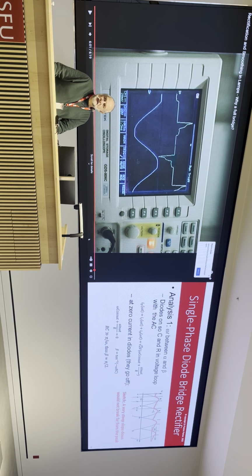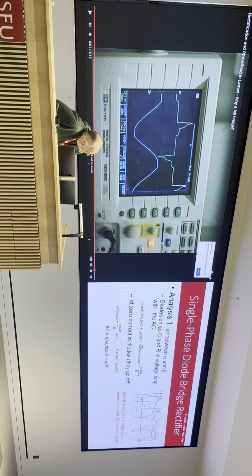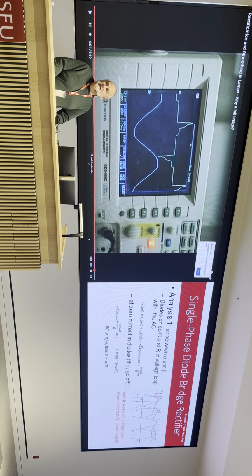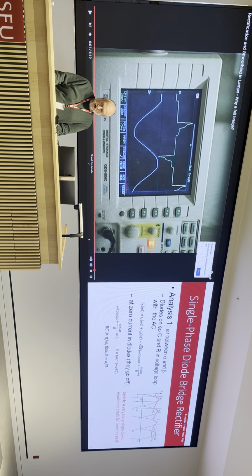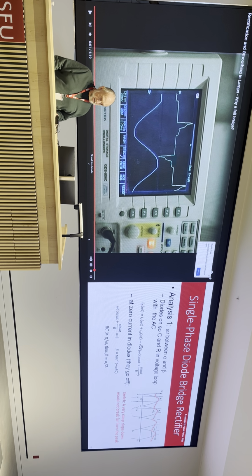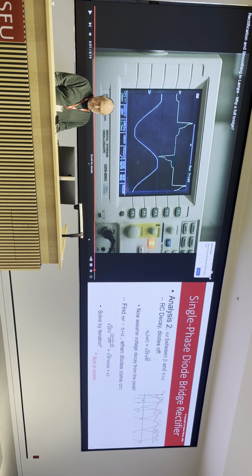So a peak diode current on a capacitor smooth bridge rectifier would be a typical type of question to think about, okay? And of course that diode current also has the sine omega T upon R. It has the resistive load component as well. Anyway, I hope that bit was a bit of fun. Let's go through here.